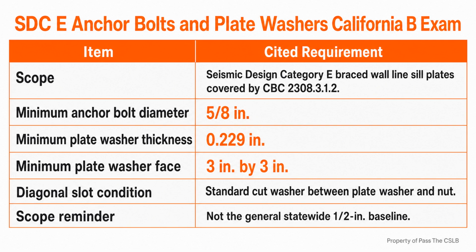Think of a floor diaphragm as a broad surface collecting a sideways push. The force spreads through the sheathing, then has to be gathered at supported panel edges and delivered into the designated vertical elements. Blocking, framing connections, and the approved fastening schedule create that handoff. If the floor is stiff but the edge connection is incomplete, the force has no reliable route into the wall below.